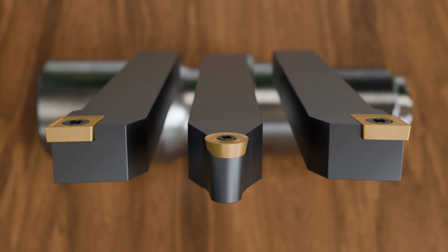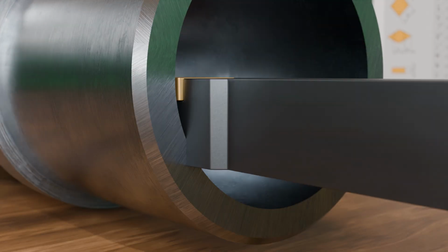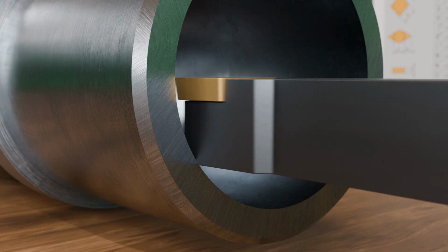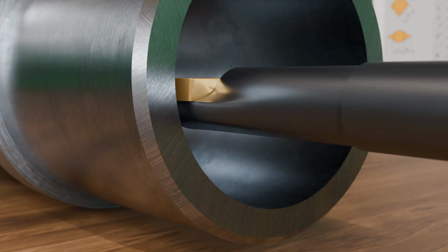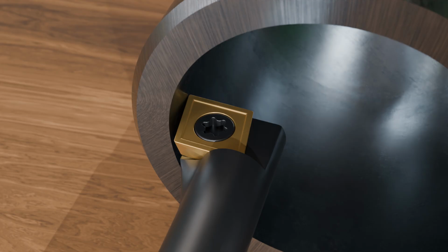In all cases considered so far, the workpiece was machined from the outside. However, internal geometries can also be produced on a lathe. Turning tools for external contours are not suitable for this purpose. Due to their rectangular shape, they would collide with the internal surface. Therefore, internal turning is done with special internal turning tools called boring bars. Boring bars are usually made round so that they do not interfere with the internal shape of the workpiece.